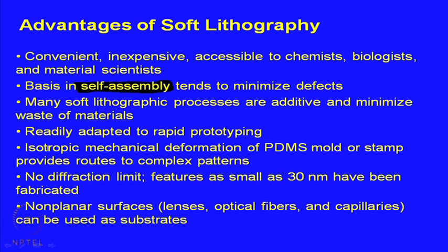Isotropic mechanical deformation of the PDMS mold provides a route for complex patterns. There is no diffraction limit. This is extremely important. Photolithography is significantly limited by the diffraction of the wavelength of the light source you are using, and not even 30 nanometer, features as low as 10 nanometers have been achieved way back in 2005 itself.